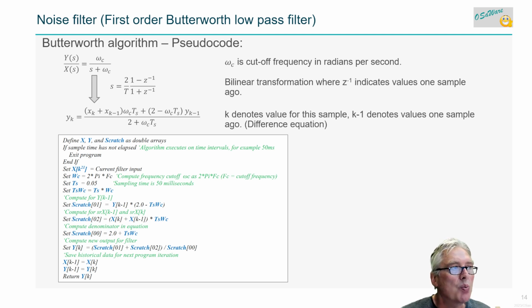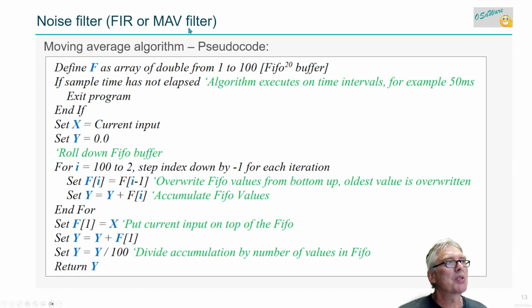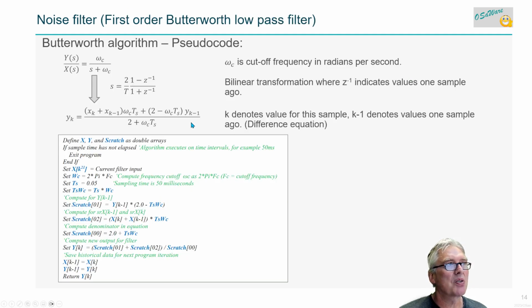Remember, they are recursive. You call it once, and then you have this k-1, which was the last value, and then you call it another time after a sampling period and do a new calculation, get a new k-1, and so on. So this is something we call an infinite impulse response filter, because here we are always basing it on the old signal that we calculated, and that is never going to turn to zero in theory. But of course the numeric resolution of your CPU, if it's 32-bit or something, is eventually going to make it die out, because you can't represent the small numbers. In theory, it's never going to die out. So we looked at two here: the finite impulse response, or moving average filter, which is a special case, and here's an infinite impulse response filter. That's a better filter, and that saves old calculated values. It depends on what I calculated the last time.